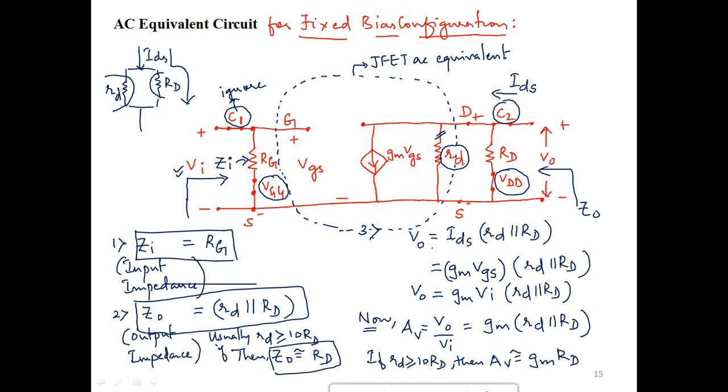Now one small thing is missing here, that is the inclusion of the negative symbol. Okay, for an n channel MOSFET, if you look at the notation of the current source and that of this IDS, you will observe that we will have to include a negative sign here. Okay, minus.